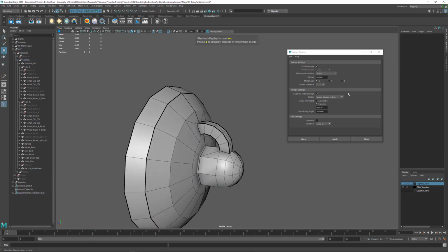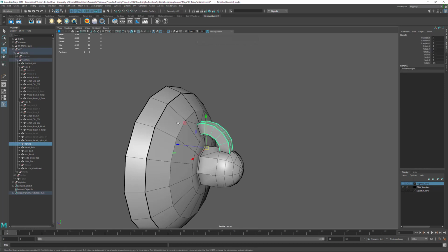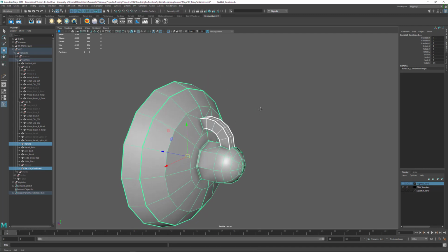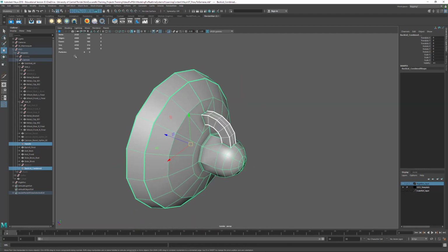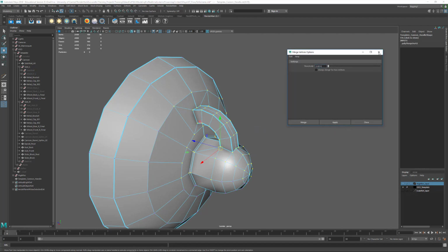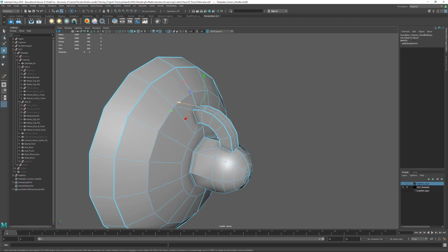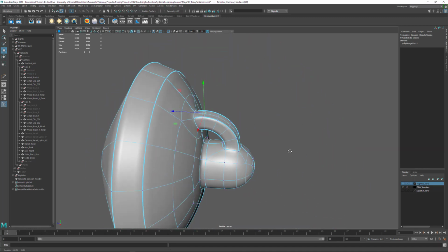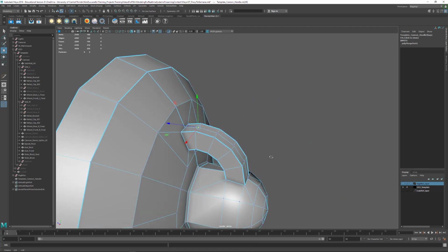And now, let's combine this together with this. Okay, I'm going to take the handle and the back lid and combine them. So we're going to go mesh, combine, like that, delete history, Alt-Shift D. And then let's select the verts, F9, drag a marquee on this, shift right click and say merge vertices and do it with a really low threshold, and that should weld everything together. So now if we tap 3, if we did everything right, it should kind of smooth out something like what you see here. And that's kind of a pretty cool look.